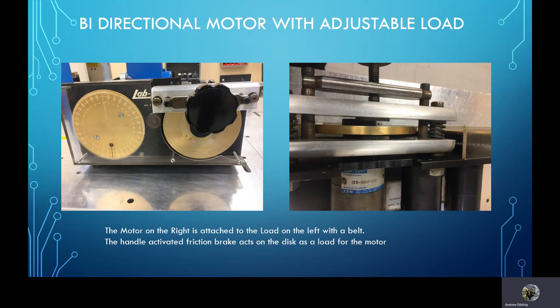Now this is a fixed displacement motor that we're using. So the fixed displacement motor would be better used where I have a very predictable amount of force required, and it really doesn't change much. If I have a requirement for a speed variation over a wide variety of loads, I am probably going to go with a variable displacement motor and a speed control as well.